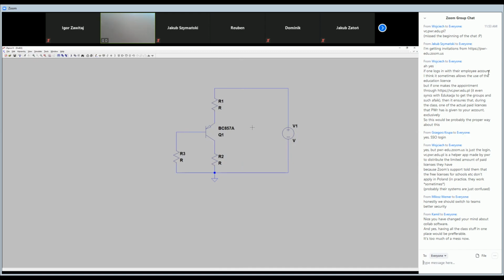Yeah, I've got it. The emitter resistor is equal to 99.4 ohms. The collector is 1 kilo ohm. And the base resistor, we found that it is equal to 282 kilo ohms. Great. The supply voltage is 10 volts. Okay, I've got it.